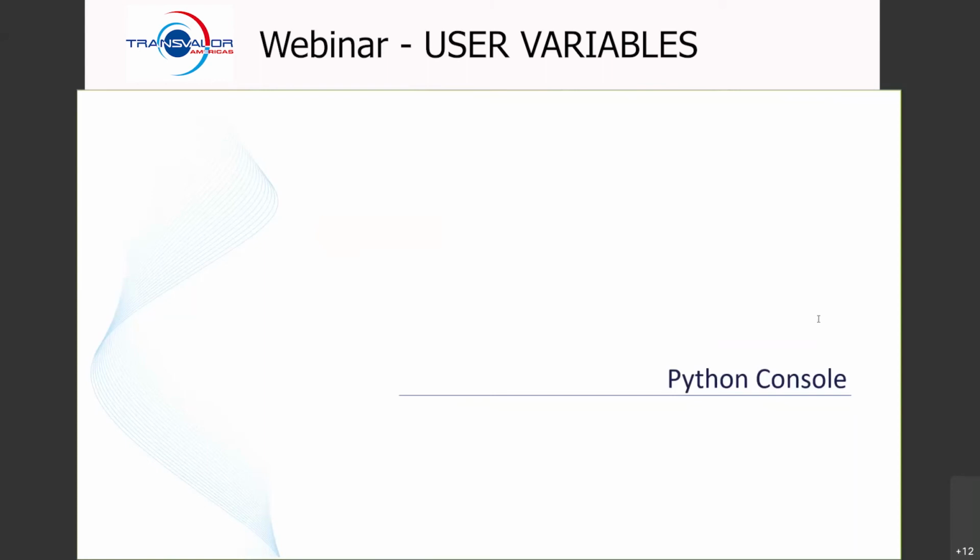like a result that you will have at every increment. Okay, and that's specific point. I want to clarify there that these user variables are shown in every node or every element in the model. So this will be calculated everywhere in the billet, okay? And the temperatures are specified by you. So it's not going to use the maximum temperature on the billet. It's going to go to each element or each node and start counting the time once you reach the first temperature until you reach the second temperature.